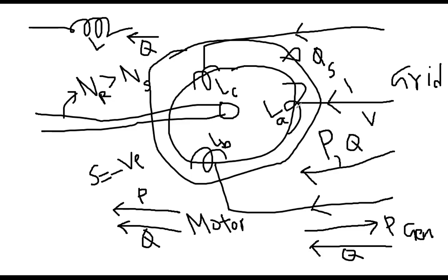And what is the consequence of having a low lagging power factor? The consequence is that there will be some voltage drop at the terminals. Voltage will go down as there will be much more loss in the system. But then I said that you must send the reactive power to produce magnetization, to produce the magnetic field. But then what is the adverse impact? The adverse impact is that the power factor will be low lagging. And the consequence of that is voltage drop. So then how do we handle that situation?